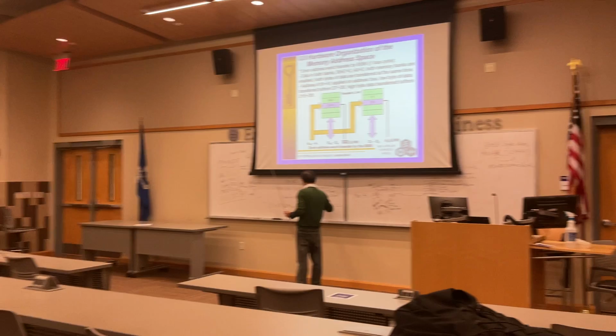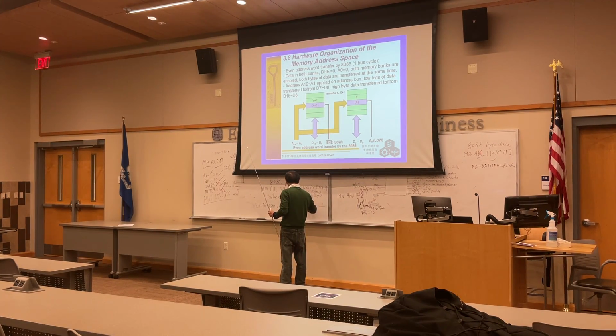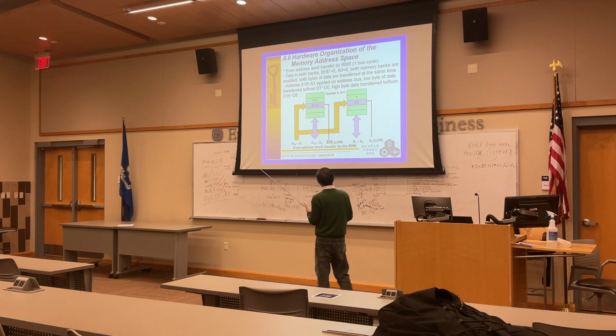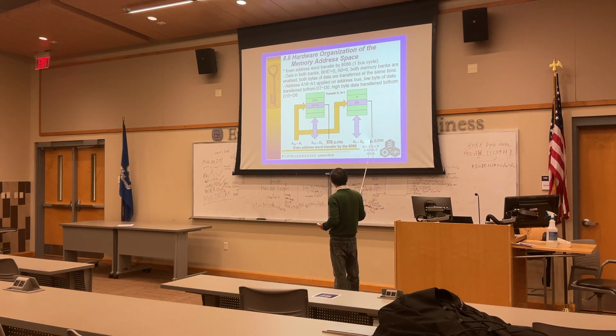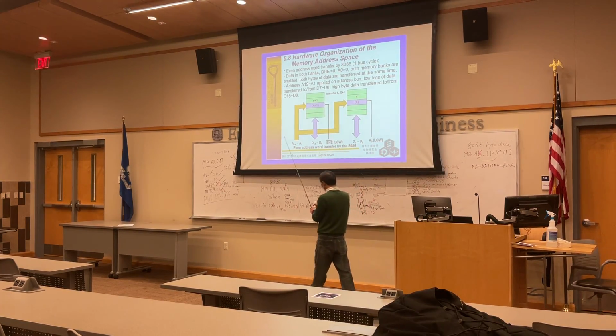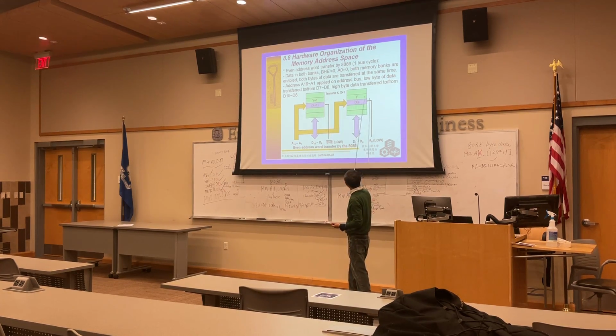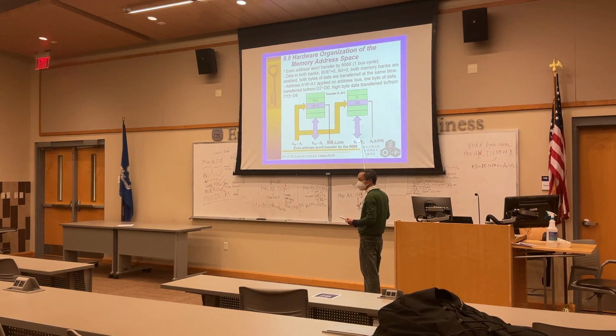The physical address is 1234H plus DS, going out on A19 and so on. This is an even address, so A0 is 0, enable, and we also set BHE to 0. We simultaneously enable the lower byte and higher byte, get both, and send them to the data bus, D0 to D7 and D8 to D15.